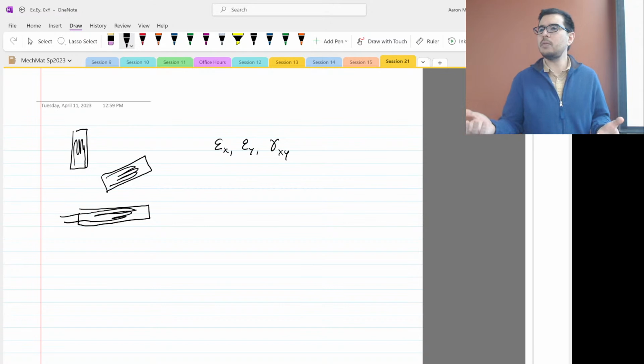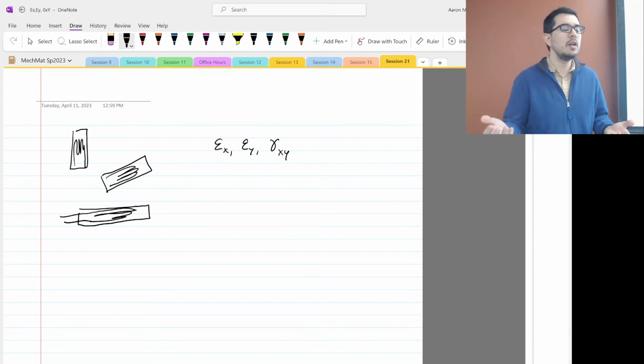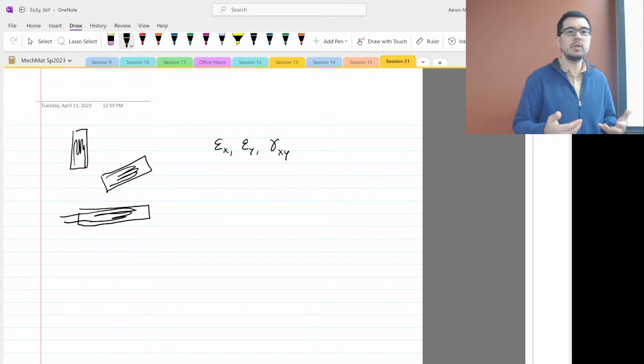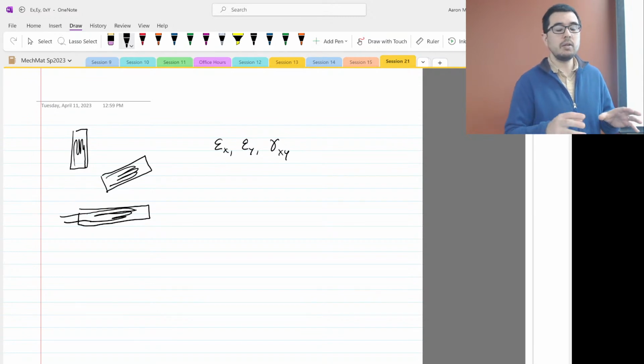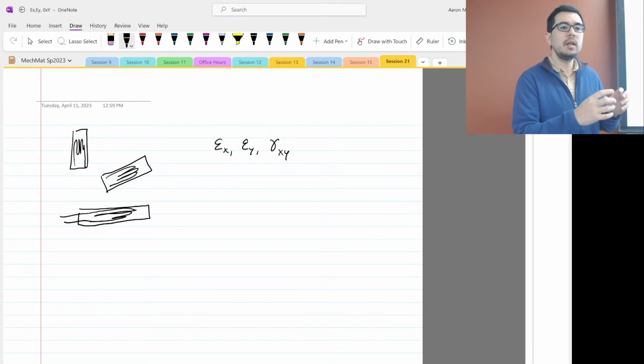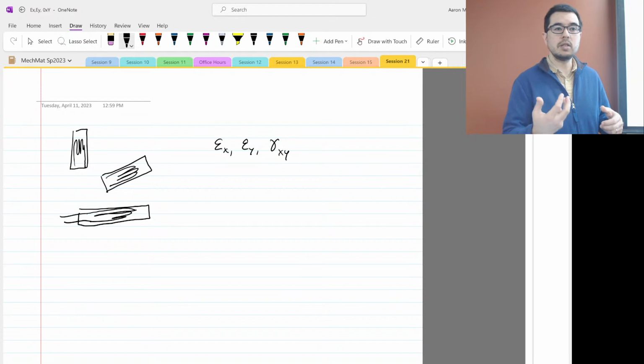Has anyone used strain gauges before in this? Okay, so our lab has worked with strain gauges a little bit. We've made some wireless ones where we're attempting to measure a change in electrical impedance. In the slides we call it resistance, but we were actually looking at systems where we have AC current that we put in a coil that then gets transferred through induction to another coil, okay? And then it runs through an element that is sensitive to strain. And then we pick up those changes in impedance, right?